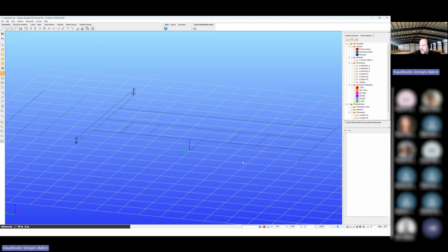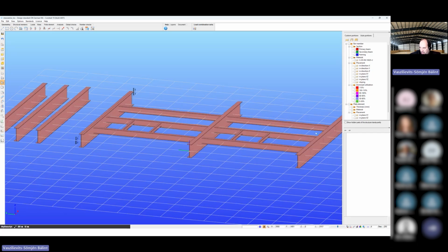In Consteel, we always say that it's very important to work with eccentricities. Therefore, we never recommend keeping a model like this, because if the model is kept like that, then all those parameters we try to obtain from the model, mainly for the buckling verification and second-order analysis, might not necessarily be as accurate as they should be. So what is important is to really set the eccentricities.